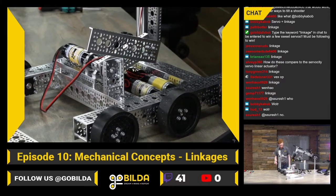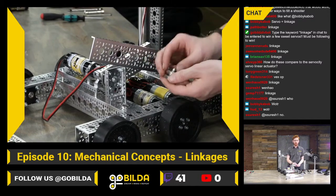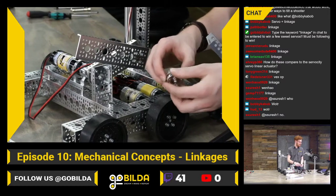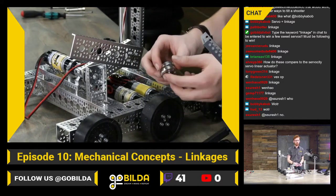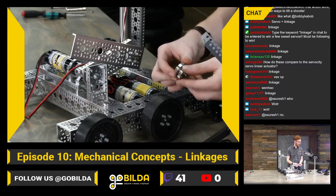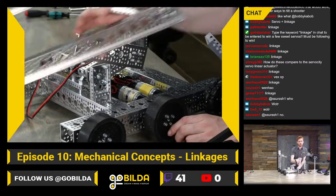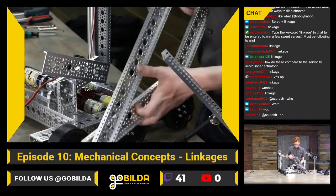Those are a really fun part that we designed. They're just a collection of parts. None of these were special made for this pillow block, but it's got a thrust bearing and 2 standard bearings, so it can really, really effectively take a lot of side load and still run pretty smooth. That's what I'm using in all the joints here, and I think that turns out really, really nice.